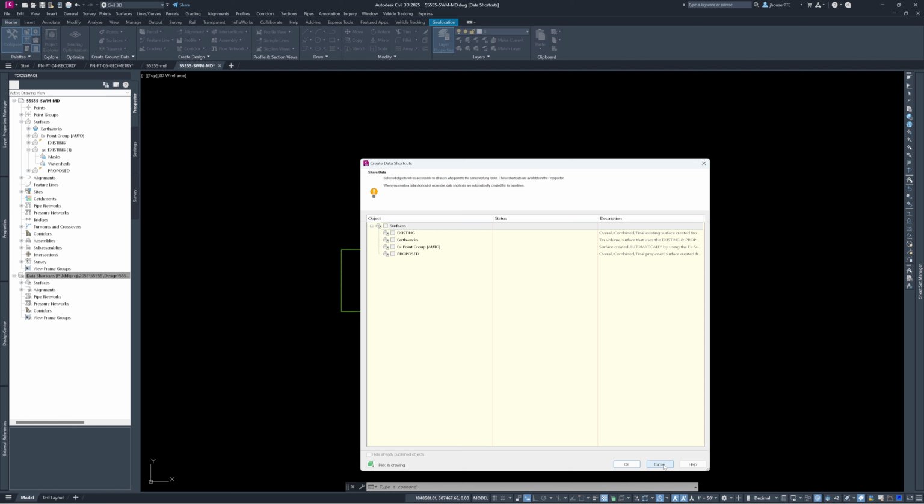So in our old system we would have created a surface in the MD, we'd have done a lot of stuff in the MD, and then we might have done a save as for the environmental, and they would have done their design over there. Now the issue with that is design's still working on it, and they found out, hey, something changed dramatically with our surface. The only way to get that information back to environmental so they know that it's updated would be to do another save as or an XREF. It gets convoluted and gets confusing, and there's a better chance of us missing a change that could cause issues in the future. So data references are very important, very useful.